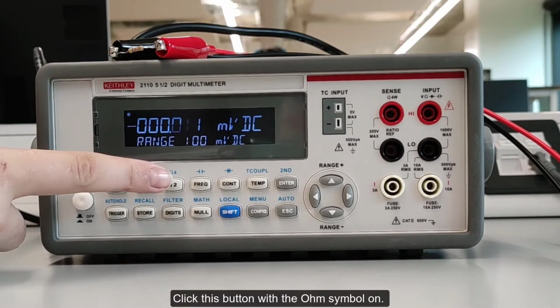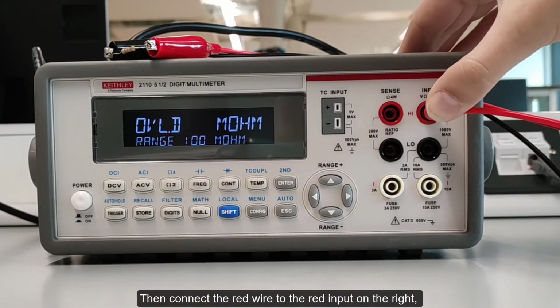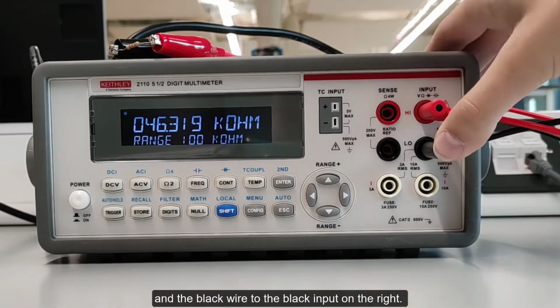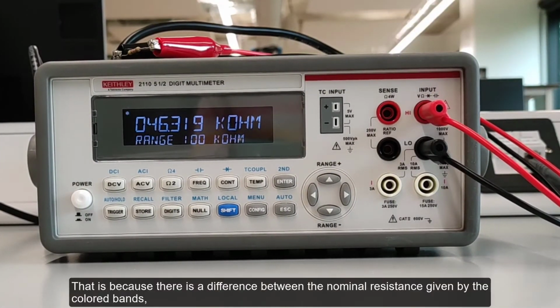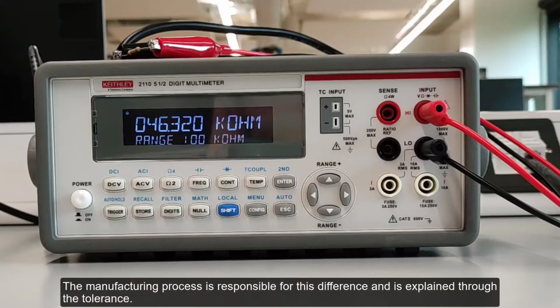Click this button with the ohm symbol on. Then connect the red wire to the red input on the right, and the black wire to the black input on the right. The device reads 46.3 kilo-ohms. That is because there is a difference between the nominal resistance given by the color bands and the actual value of the resistor. The manufacturing process is responsible for this difference and is explained through the tolerance.